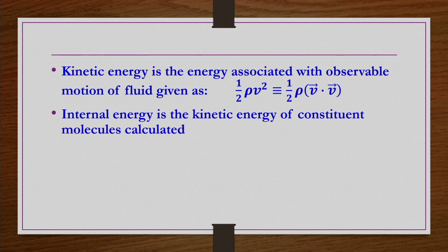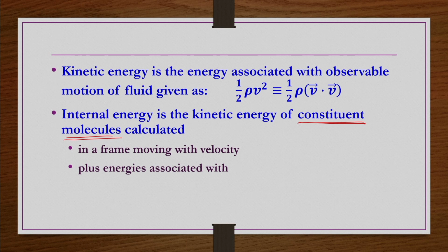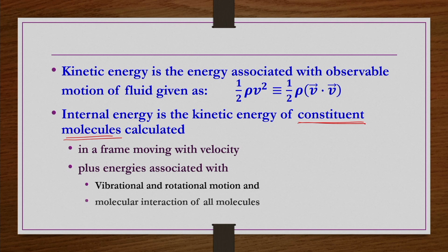Whereas the internal energy is the kinetic energy of the constituent molecules, whatever the molecules constituting that fluid. Whatever the moving fluid is, the molecules may be constituting some kinetic energy. So, that internal energy of that system is nothing but the kinetic energy of constituent molecules calculated in a frame moving with velocity, plus energies associated with the vibrational and rotational motion along with the intermolecular interactions of all molecules. So, all these things are included in the internal energy part.